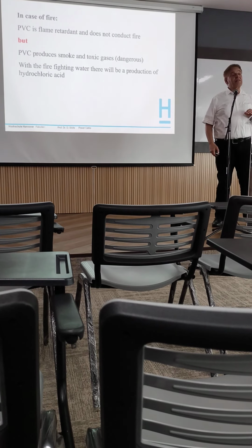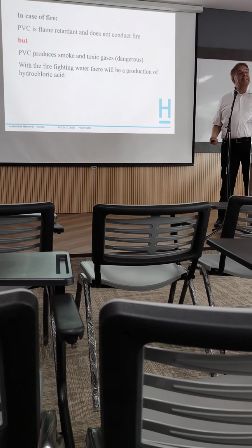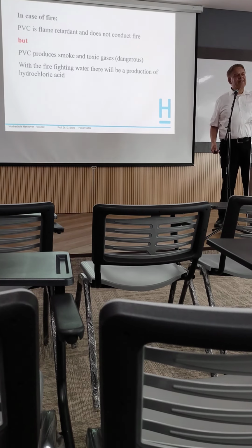When a firefighter comes, they usually fight with water. But we have PVC, polyvinyl chloride. What about the chloride? We have the chloride together with water. The chloride together with water will become hydrochloric acid, Salzsäure in German.